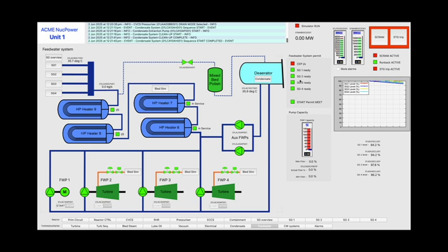We cannot start a feedwater pump yet as steam generator levels are still too high. Feedwater system permit to start will not be met until levels are less than 70%. We can skip forward as this may take some time. Start feedwater pump 1. This pump is electrically driven so can be started before reactor can make steam. Feedwater system will also go through a cleanup routine.